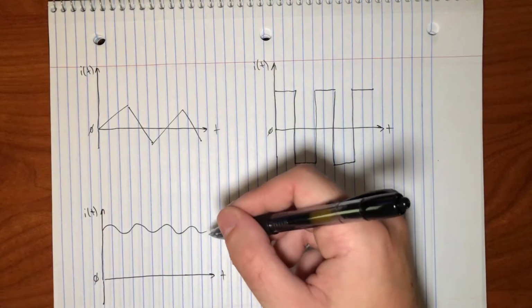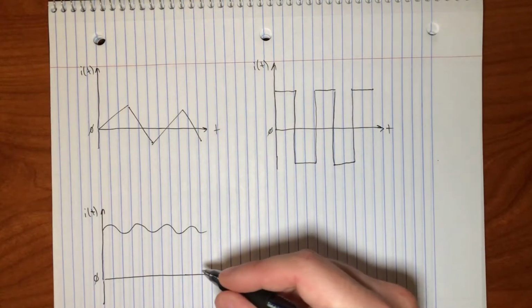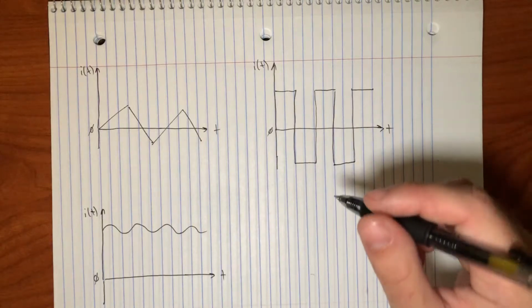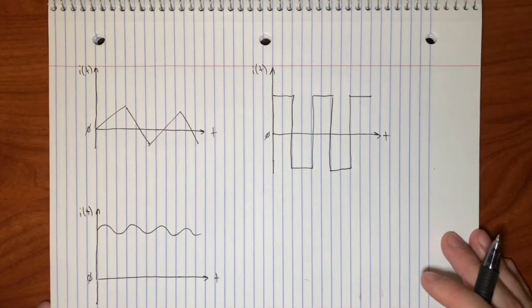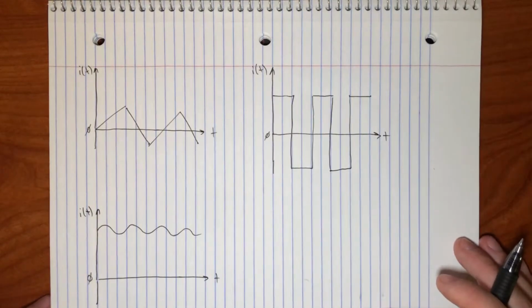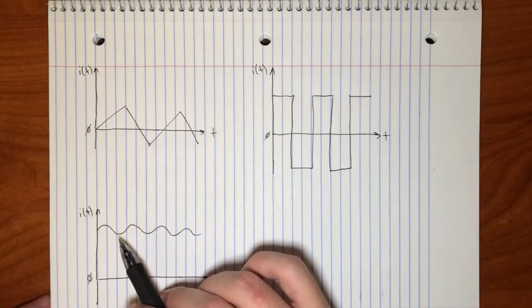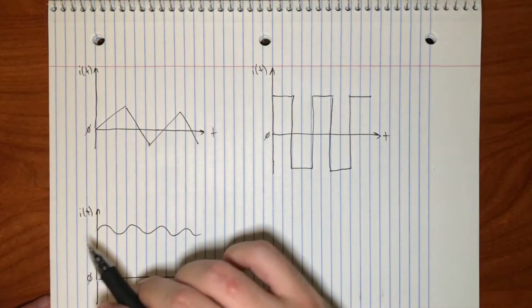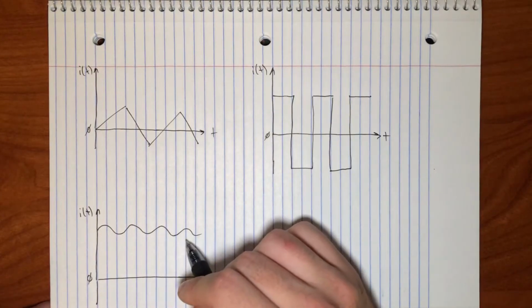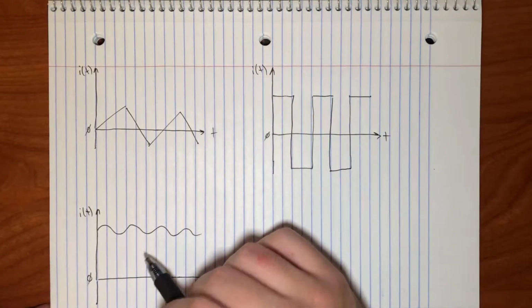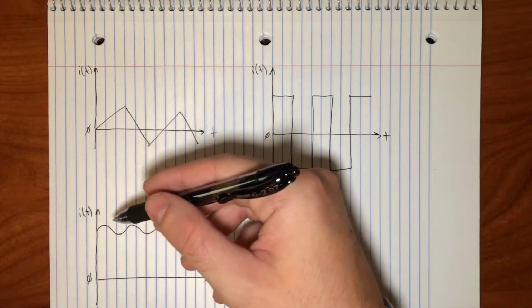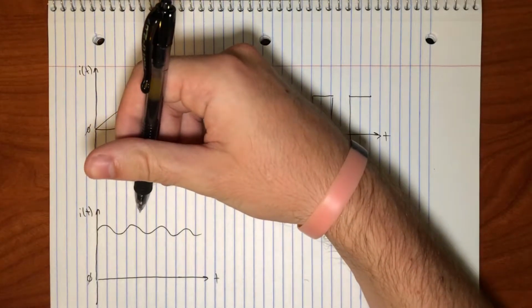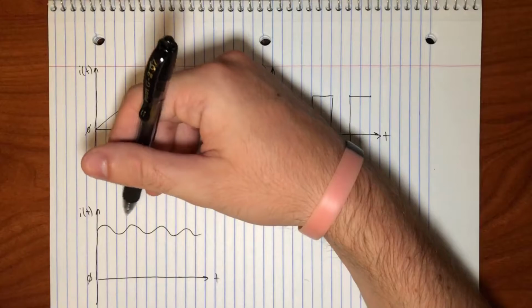Now this can get kind of hard to visualize, but if you imagine a circuit, what you're really seeing here is a net positive flow. So if you have a DC current, one thing to remember is that that current just flows in a single direction forever, or as long as it's DC, it just flows in a single direction. Now this current, although there is this ripple, does it ever actually change direction? And the answer is no. It may vary in amplitude in the direction that it flows, but it never actually changes direction. So this current as a whole, you can't say it's AC. But is it DC? Well, not exactly.